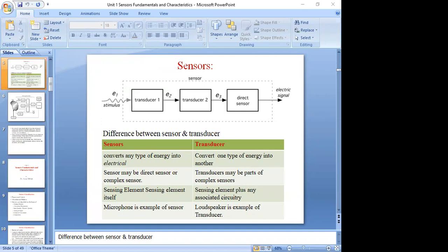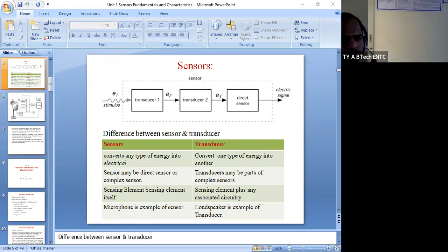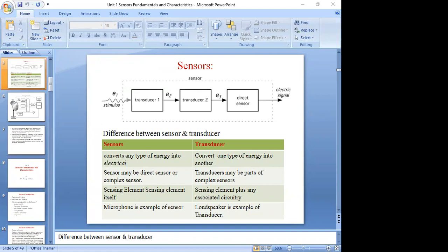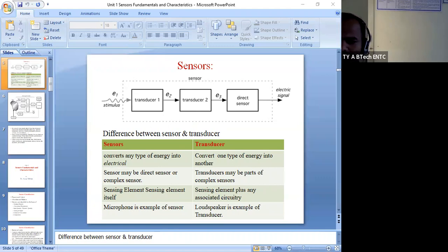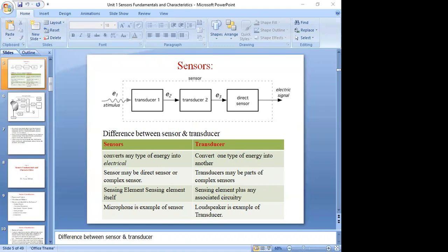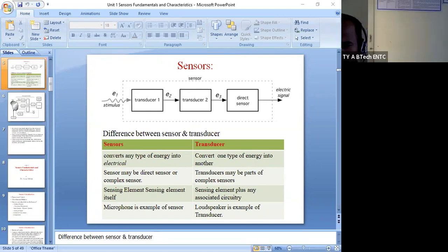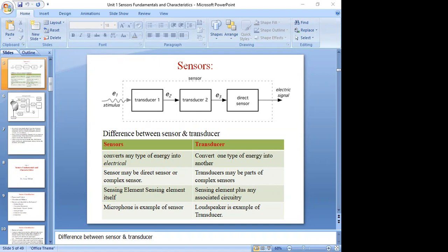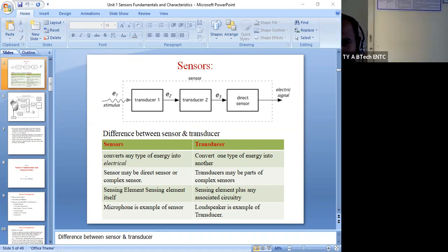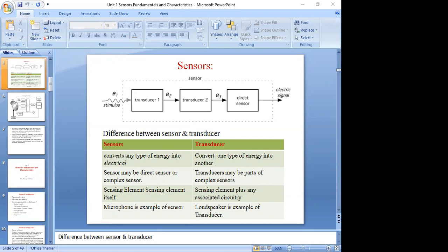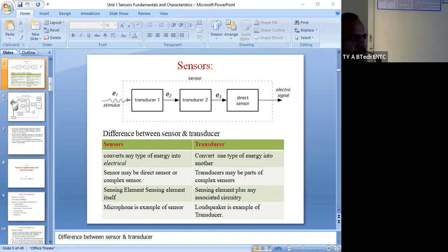8:3. Why 3? Yes, please. No sir, there will be 3 select lines. 8 to 1 needs 3 selection lines or control lines, because here 4 to 1 is not sufficient. Right or wrong?